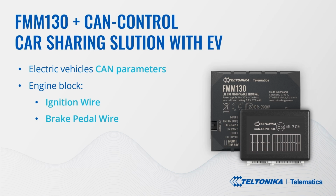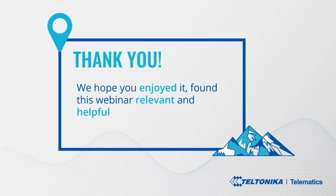For ignition blocking, we suggest two ways: to connect a relay to the ignition button wire or to the brake pedal signal wire. For car sharing, it is a must to have the possibility to see door status. You can easily control it with the central lock control, just need to send a command to the server to lock all vehicle doors.